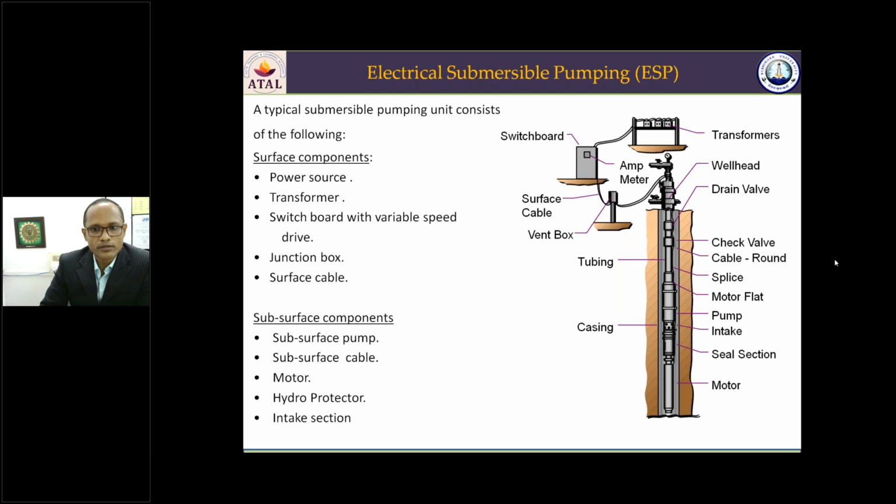So we now see the motor. There is a submersible motor here. The electrical energy runs the motor. This is a submersible motor. It's a two-pole, three-phase squirrel cage induction motor. It runs at a nominal speed of around 3,500 RPM, and it is filled with some kind of oil to provide the lubrication and the thermal conductivity.